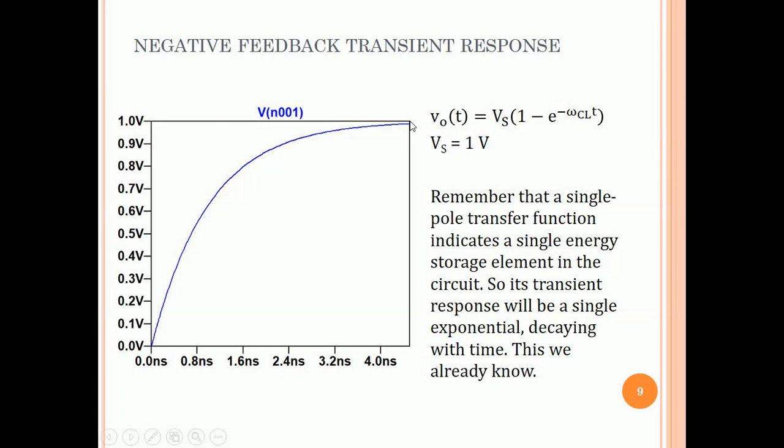Now, of course, a single pole transfer function indicates that the circuit has a single energy storage element, and we know that a single energy storage element will have a single exponential in the transient response.